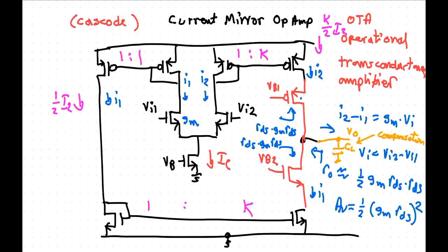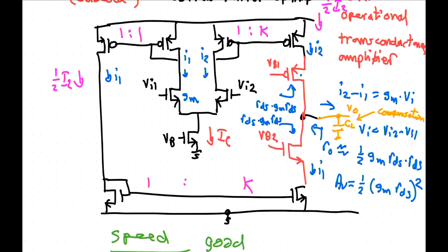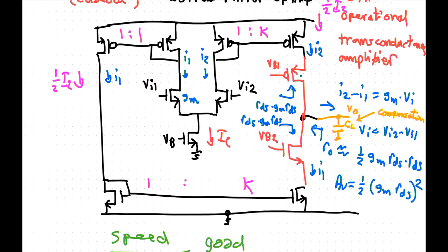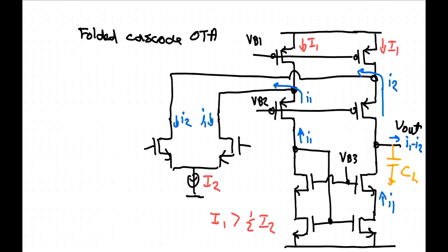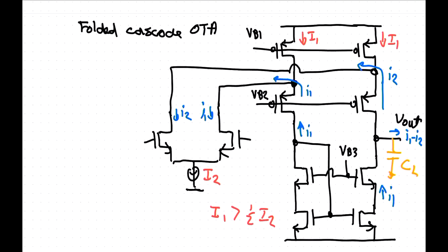Now that doesn't happen in the other circuit because of the structure. Right now it's a half, and the one below it's like a... Yeah. So all this doesn't suffer from the gain point of view from putting current in the diff pair, whereas the other one does. So normally in the other one you make K larger than or equal to 1 for sure. You don't make it smaller. Whereas here you might have 80% of the current in your diff pair or something like that.